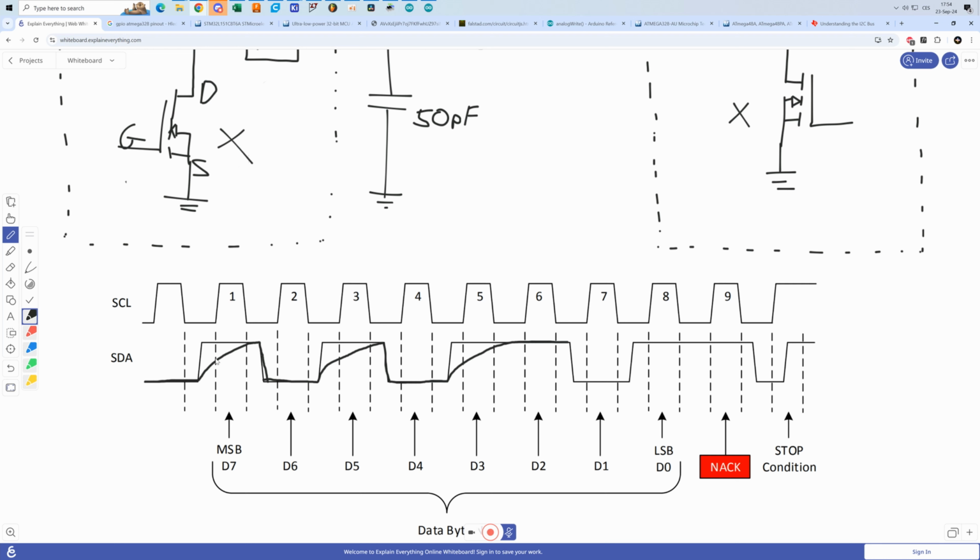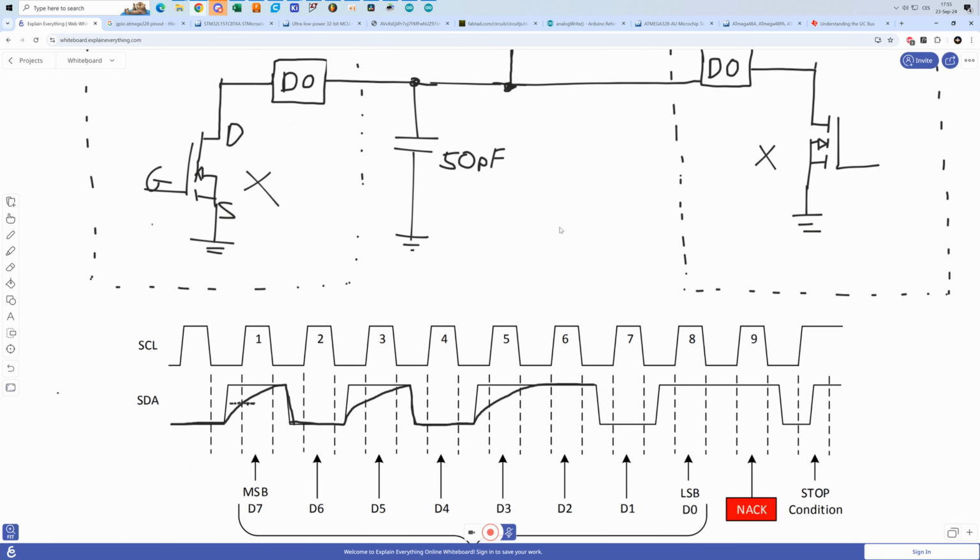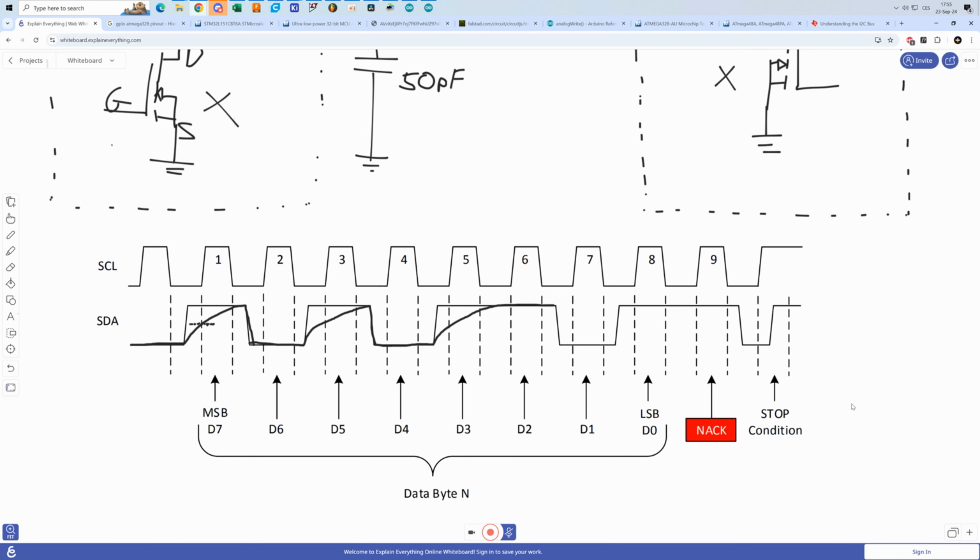And notice what can happen. This can be a very big issue because we are here on the rising edge of the serial clock. We are reading the state of the serial data line. And at this time, we can see the voltage is somewhere here, which may not necessarily cross the threshold for logic high. So even though we should see logic high on the data line, we can still have logic 0. So the message that we want to send will be distorted. So this is a problem, and there are not many solutions to this problem.